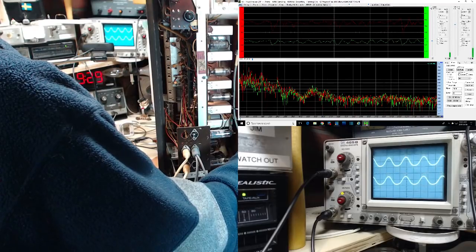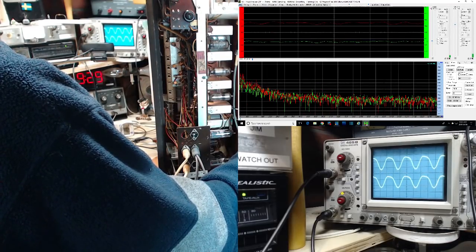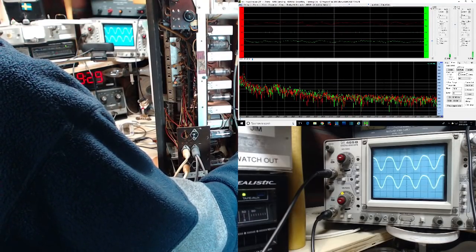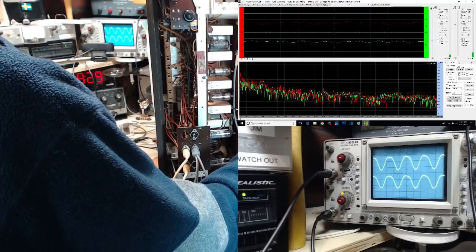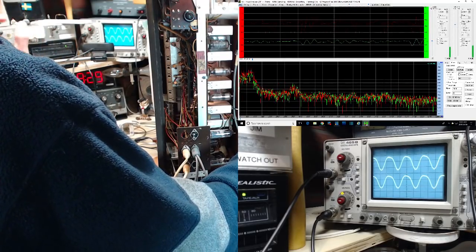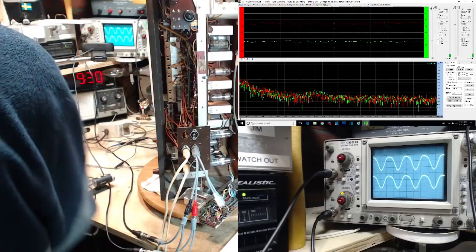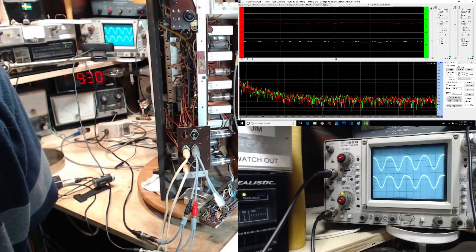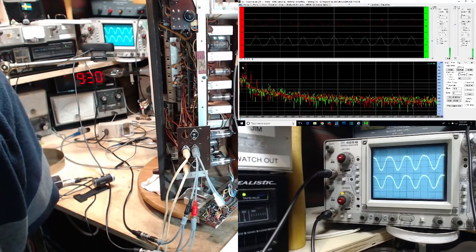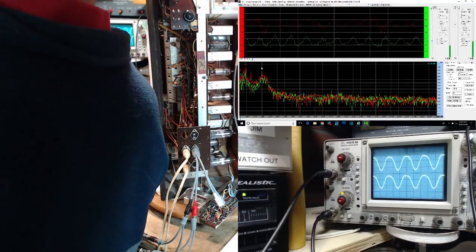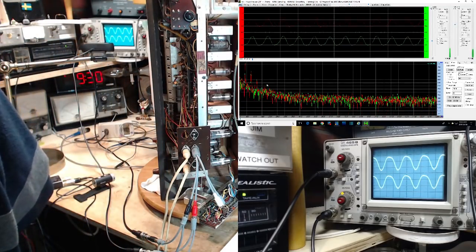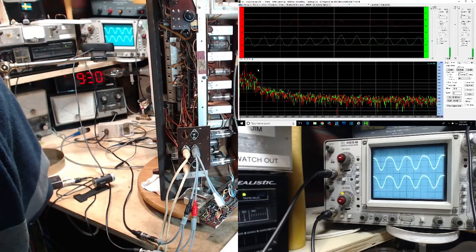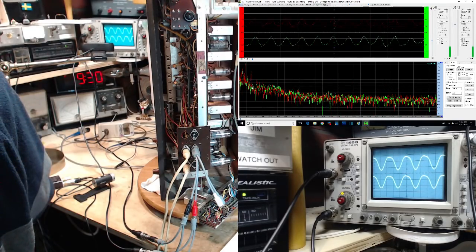Okay, so let me put it back to the lousy shape it was in, something like that. Now we're going to turn up the spectrum display and try the same thing. This time just concentrating on the harmonic peaks, which are now all squeezed on the left side of the screen. I'll show you with the mouse here. See, they're all over here. That's the primary, and these are harmonics. We want to adjust that and see if we can make these just kind of disappear.